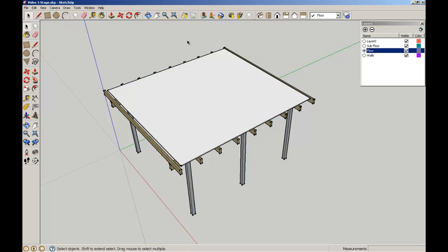Now, working between layers doesn't necessarily mean that the geometries of the different elements in layers are going to be distinct. So if I start making an element, say in the walls layer, and that geometry sticks to this floor plate that I've made, we are going to have some problems with geometries overlapping and distorting each other. So what I'm going to do is finish off the floor.